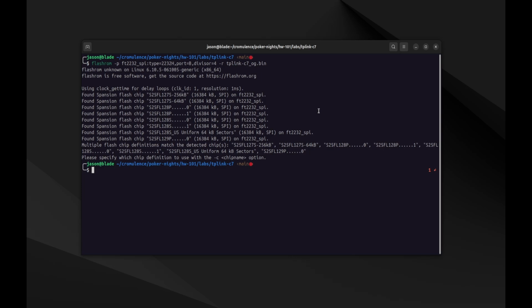What's interesting is I pulled firmware on an identical router when I was writing this up, and I did not get this, so I believe that they're actually using a different flash chip on this board than what I had used before. And this is actually kind of common, and these chips are pretty interchangeable. They all follow the same protocol and standard. But you know, with supply chain issues, they might have just had to switch to a different manufacturer when they made this batch.